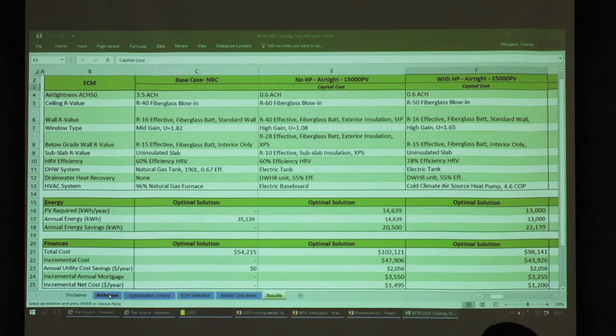And when you're going through these ECMs in practice for your own projects with the help of your energy advisor, it's worth having the discussion. Is this project going to suffer from overheating if I use high gain glass? What's my exposure? What's my shading solution, etc.? Do I need to look at mid gain or low gain options only and restrict the ECMs with that caveat?